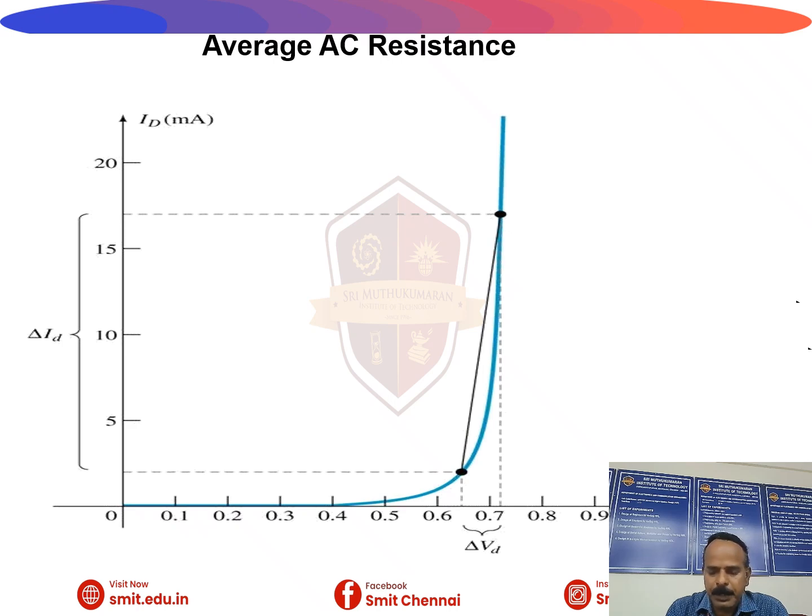But in the heavily doped diodes, the depletion region is very thin. When the reverse bias voltage is applied, a very strong electric field is developed across the depletion region. This intense electric field breaks the covalent bonds directly and generates a large number of charge carriers around the junction. This mechanism is called Zener breakdown. The Zener breakdown normally occurs at lower voltages, whereas the avalanche breakdown occurs at higher voltages.